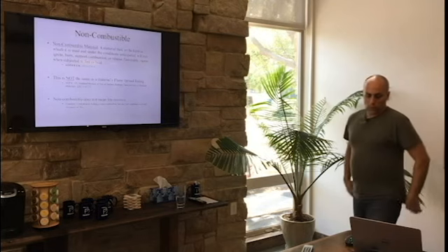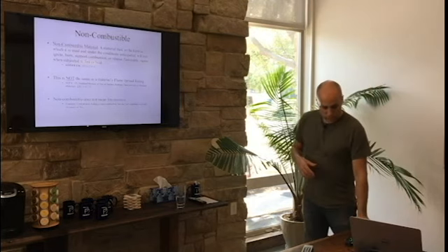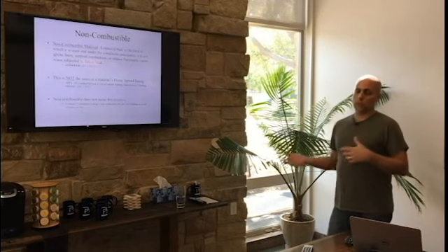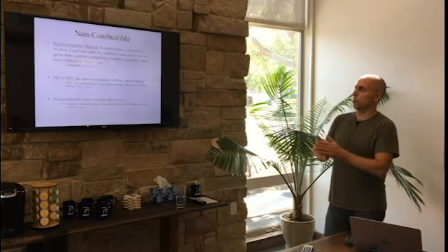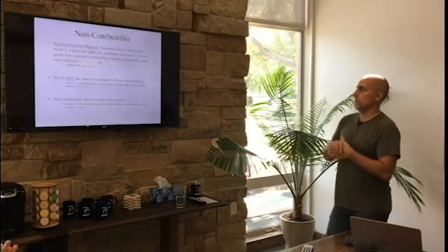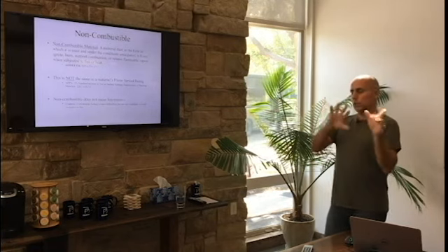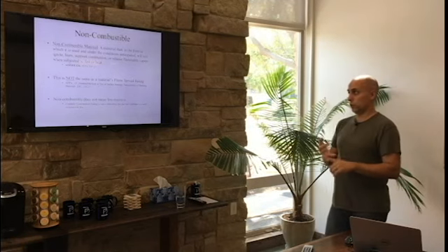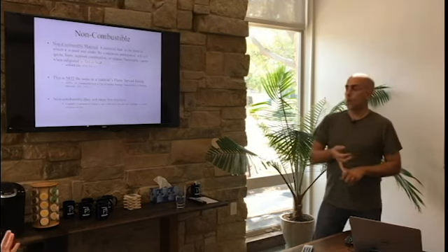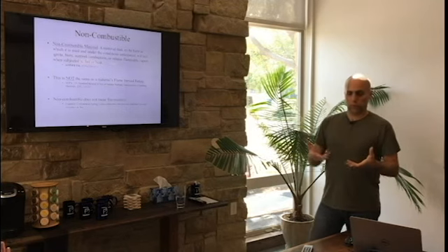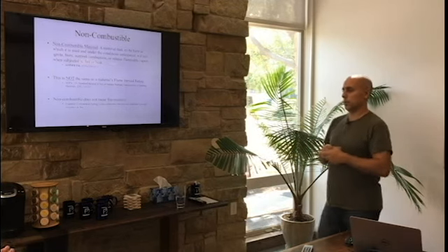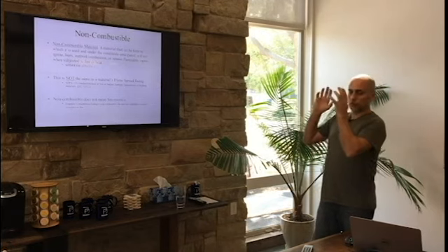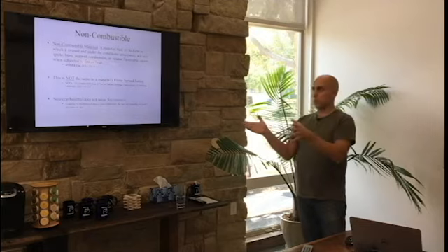Okay, so that's talking about ratings, and that's talking about the difference in construction and barriers. When we get into construction types, you have non-combustible and combustible, and it's really important to understand that. And some of this has changed, not the definitions, but what's allowed has changed. In nursing homes, we've gone from the 2000 edition of the Life Safety Code to the 2012 edition for federally funded nursing homes, and actually in the state of Texas for all of them. So non-combustible material, and this is not fire resistant, this is just non-combustible.